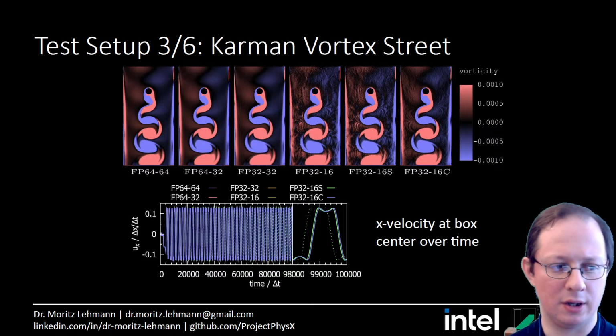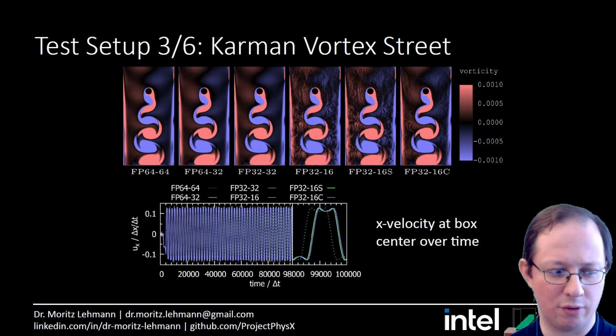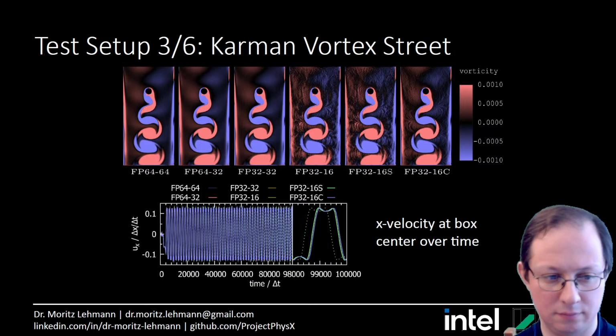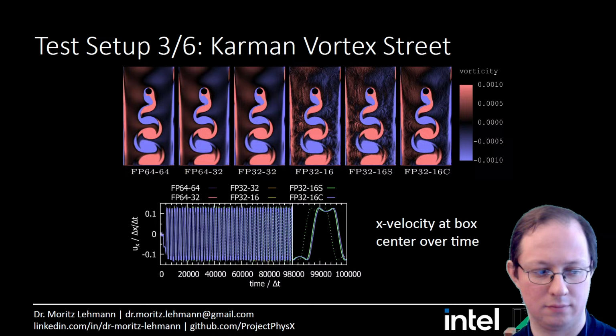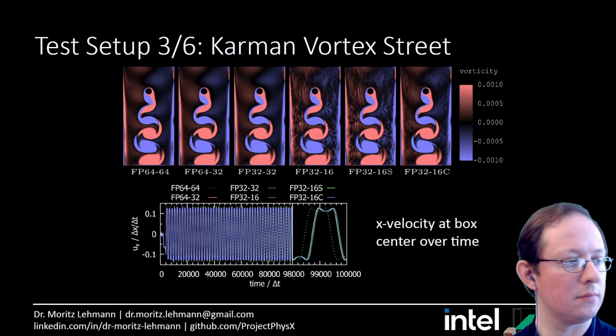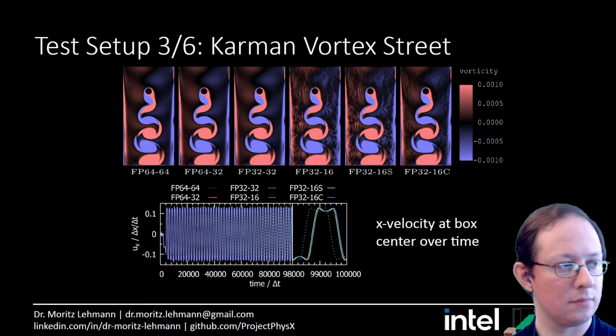Do you do a rotating frame? Yeah, it can be a bit emulated with a volume force that is representing the centripetal force. So you can set in FluidX3D with the volume force extension. A volume force is different for every grid cell.